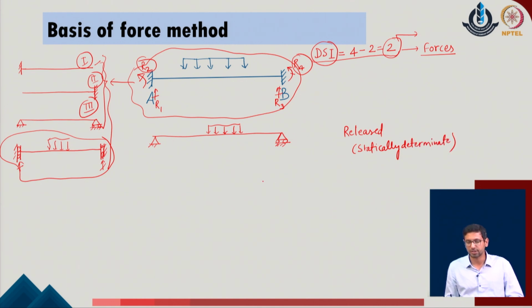Now, as we have considered the statically determinate problem having the load, I cannot say that this is the same system as the original problem. What is missing from this given problem is the condition of the two redundants R2 and R4 which have been removed. So, to accommodate them in the further system, we can again consider the same statically determinate system, and now consider that R2, which is the unknown redundant or the unknown reaction of the original problem, has been provided to this given system, and we consider this now as the external load to the given problem.